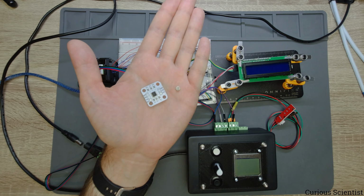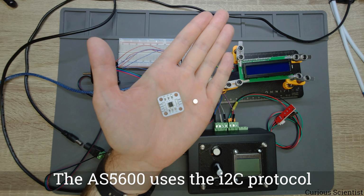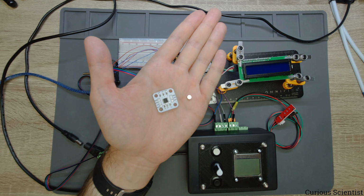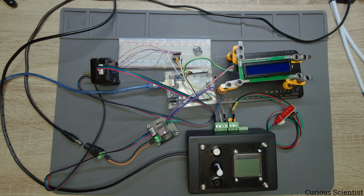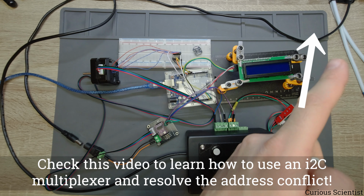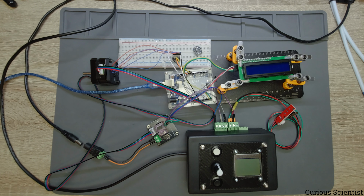This guy is an I2C device, and it has a drawback that it has a fixed address. So if you are not using any kind of special circuits, you can only use one at a time on one I2C bus. Of course there is a workaround for this, and I showed this in a video which you can see up there in that corner. If you have an I2C multiplexer, then you can use 8 or even more if you have more multiplexers with a single microcontroller.